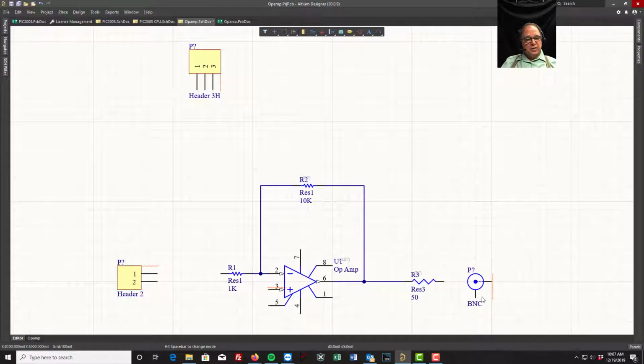The same here. The bottom pin over here, I'm going to move this designator. The bottom pin here is ground. I could wire this coming around like this. It's not going to look that good. Why don't we just hold our mouse key on it and hit the X key, and I can mirror it. So now, look at that. I can hook it directly. It looks much nicer. I'll put that B and C back up here.